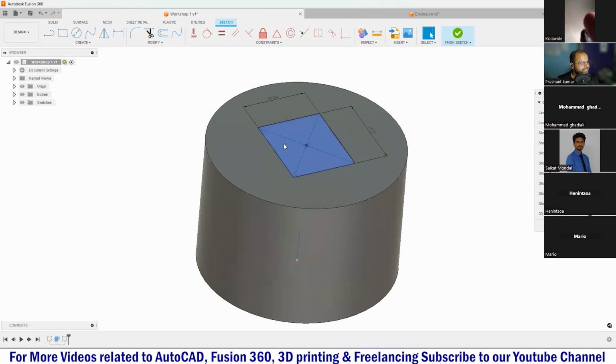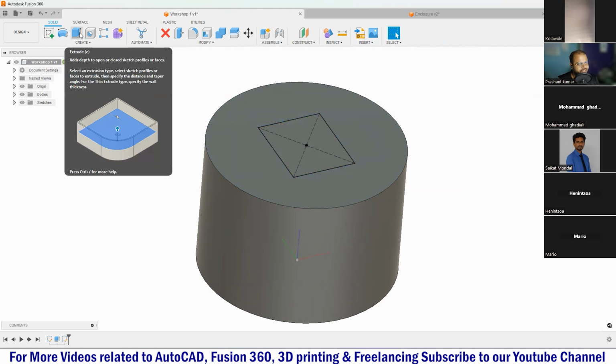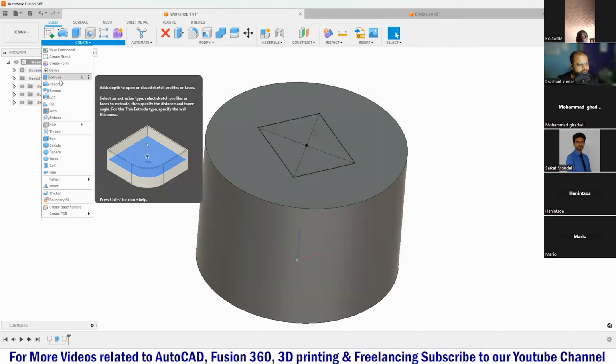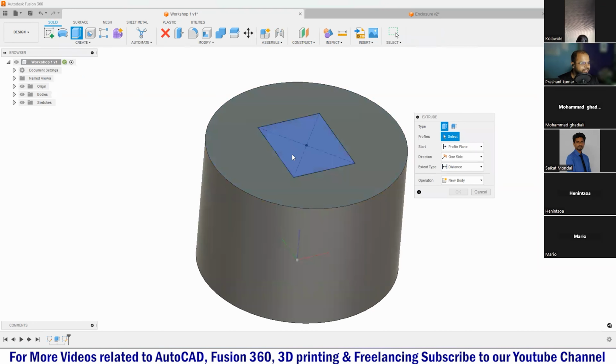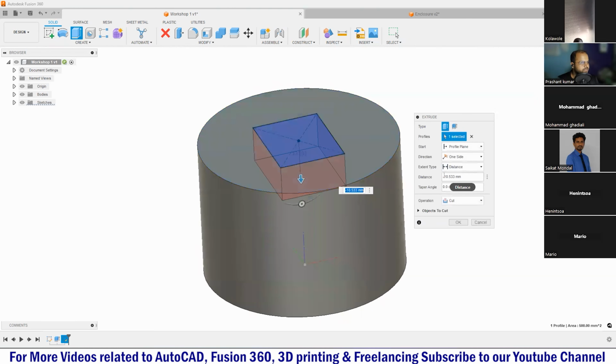Since we are done with this shape, I can click on finish sketch and again activate my extrude tool. I will select this profile this time, and I can drag it towards the bottom if I want to make a cut, right? Here you can see I'm making a cut. Just give a dimension of 10. And the moment I press OK, here you can see in operation, we have to select cut.